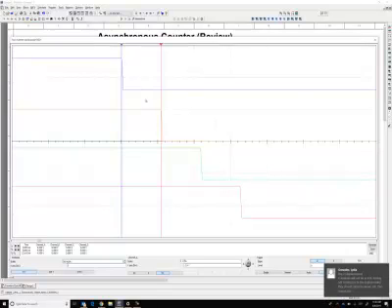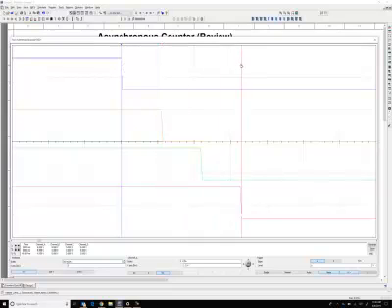However, if we have a counter that is used for something very important, like a medical device or something like that, then these are not going to be adequate. Let's say I'm having laser eye surgery. I want to make sure that those numbers are accurate because I'm dealing with very, very small numbers. So what we're going to learn today is how to make a counter that doesn't have this propagation delay issue that occurs with non-synchronous counters.